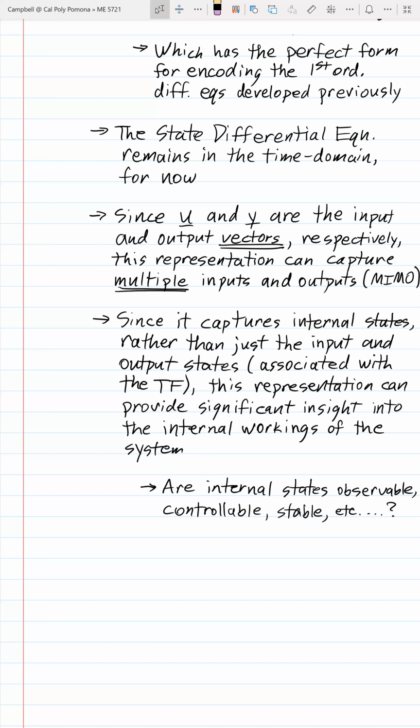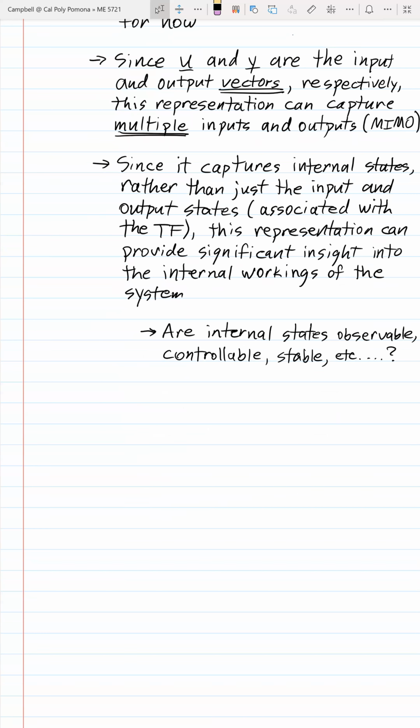Because this behavior of essentially saturated instability has been observed so much, it's actually given a name called limit cycling, where the particular system will swing between very high values or very extreme values associated with the state, but it won't be able to go beyond those, provided it even gets to those values, because something could break before that happens, in which case then we wouldn't actually see it. We would just see those very high values. We'd just see a broken system.